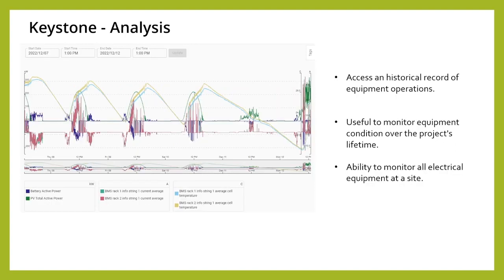If you want to get even more granular, this is really helpful for troubleshooting also. You can go down to the individual equipment level and then even the individual data point level. So we are monitoring every Modbus data point that's available, right, on this system.